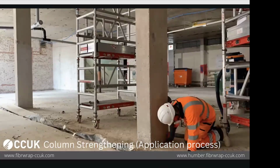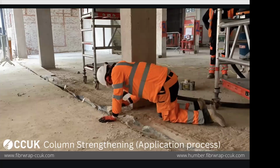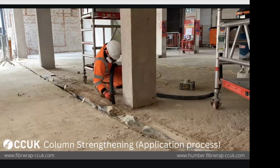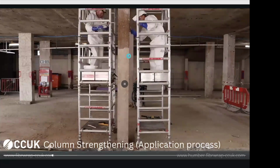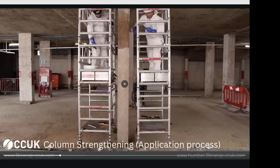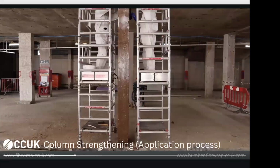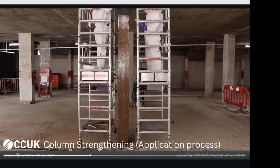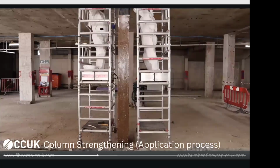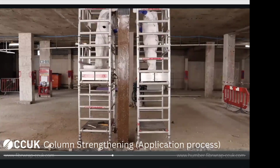So again, the same as you've seen in the slab strengthening, the first thing is surface preparation, followed by cleaning. The only additional preparation you could have in this is probably rounding off of these corners if they are not already rounded off or chamfered. That's the only additional preparation you may have to do on the column. But after that, you follow the same process. You prime it using pure epoxy, apply the first coat of thickened epoxy, then apply the first layer of carbon fiber, the next coat of epoxy, the next layer, and that's how you build up the number of layers.